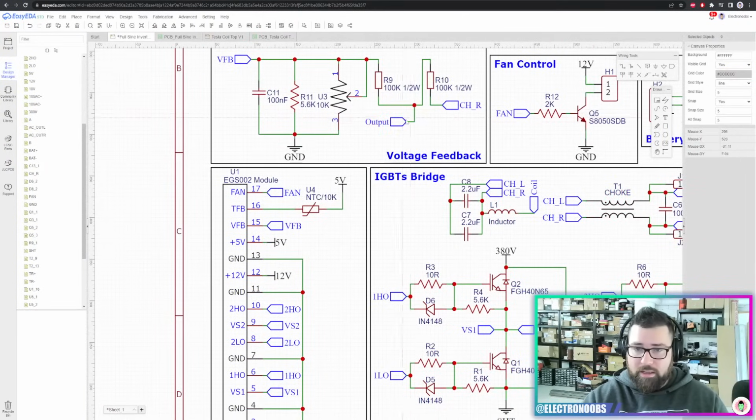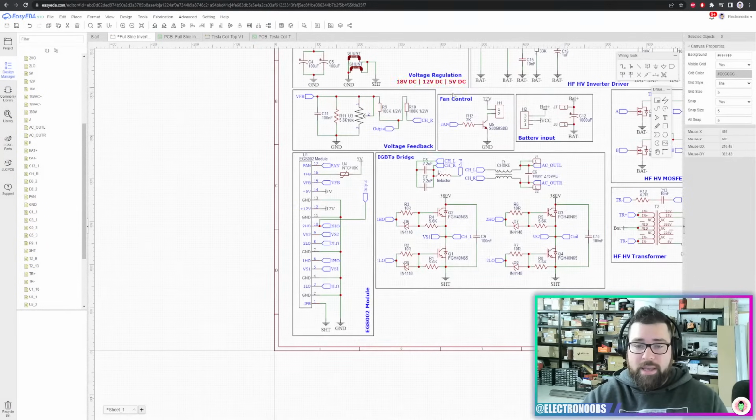Instead of just making a line like this directly to the driver, let's just connect it here. Look how ugly it is. And then it will create another problem, this dot here, and we'll talk about that in just a moment. Instead of doing just that, you can just copy this with the same name. You can press R to rotate it in any direction. You place it wherever you want on your schematic, and then you make the connection to your pin, for example, here. And now as you can see, this point is connected to this point.